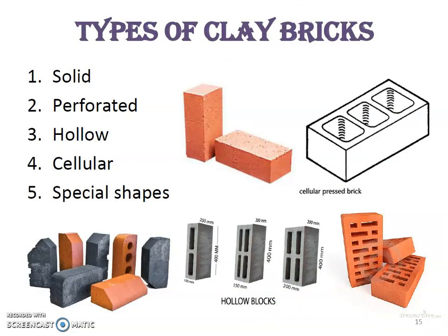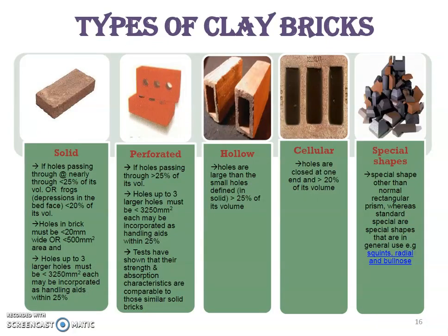Okay, we go through five types of clay bricks. Solid clay bricks are those where the holes are fewer than in the perforated. The size is less than 25% of the volume. And sometimes the solid clay bricks only have frogs, which are smaller, less than 20%.